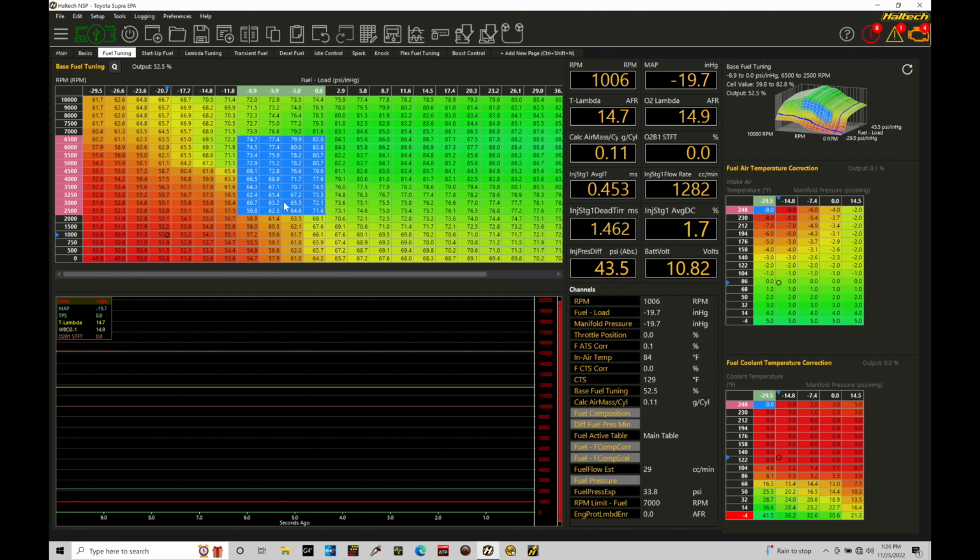We only have this much resolution in our table to deliver the proper airflow model and fueling to the engine, which is really going to produce an inconsistent fueling result and ultimately an engine that doesn't run very smooth. So we might have a problem with usable resolution because the camshaft profile or the throttle blade is so large that if we tip the throttle blade open, we go from reasonable vacuum to 0 PSI almost instantly. So there's no real usable resolution in the table.